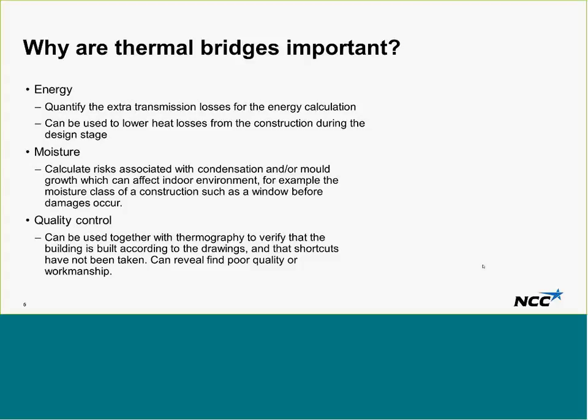From moisture risks, we can have mold problems, condensation problems. It can affect the indoor environment, the health of the people living there. And it can even affect the durability of building materials. Materials start breaking down quicker than they should. Some of these thermal bridges can be fixed if you already calculate them in the design phase.